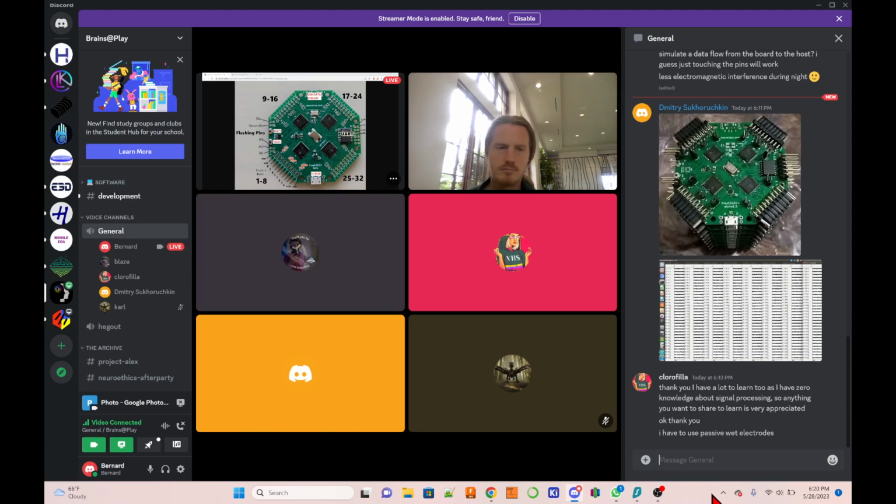Yeah, I'll give it a go. Mine are all silver rather than gold, but I think that should be pretty good as well. I'm following some stuff from a paper, so I'm sure I haven't done it as well. Silver has less impedance than gold, but silver tarnishes and corrodes. So as long as you keep them clean, you'll be better than gold. But when they're not clean, then that's the thing. Gold is actually not a very good conductor, but it doesn't corrode. That's sort of its only good quality. It doesn't easily corrode.